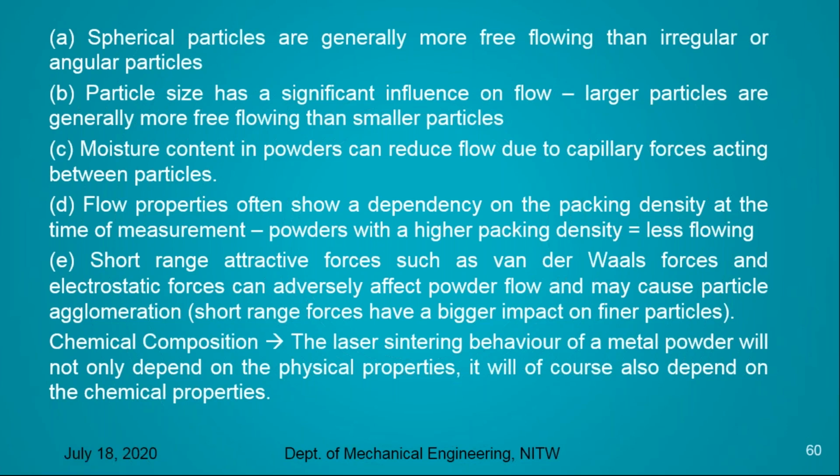For example, chemical microanalysis can be done with the help of the scanning electron microscope, the electron probe, or X-ray microscopic analysis. And bulk chemical analysis can be done with the help of X-ray diffraction, X-ray fluorescence spectroscopy, or inductively coupled plasma atomic emission spectroscopy. With these types of instruments, we are able to do the bulk chemical analysis.